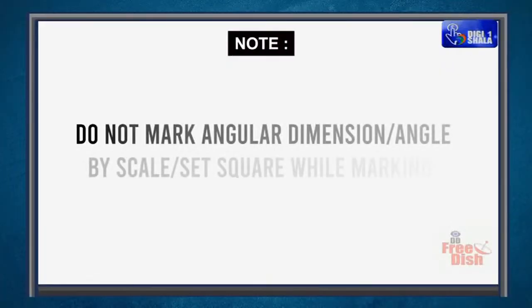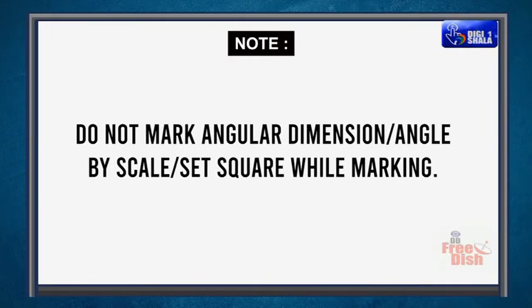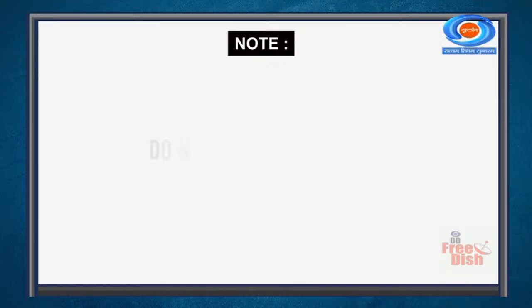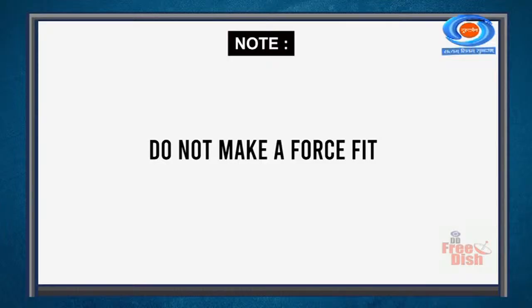Note: do not mark angular dimension or angle by scale or set square while marking. Do not make a force fit.